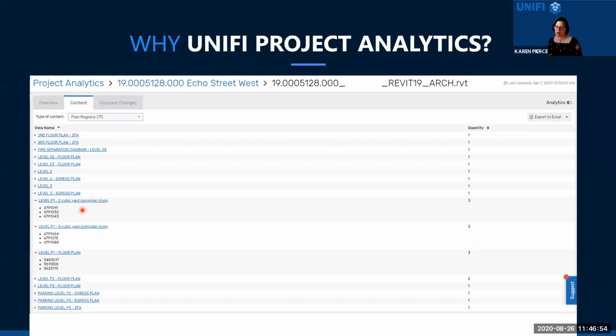So there's a lot there, and basically my way of troubleshooting visibility is turn it all on. You know, undo your view range overrides you might have, undo your view template. There's this great little thing of temporary view properties in the bottom Revit bar to hover over. Use that as a keyboard shortcut even.